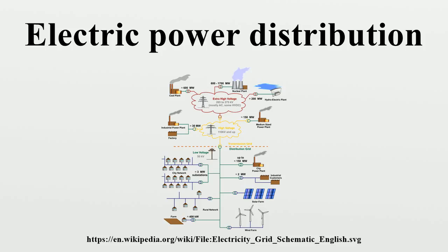Most utility customers are connected to a transformer, which reduces the distribution voltage to the relatively low voltage used by lighting and interior wiring systems. The transformer may be pole-mounted or set on the ground in a protective enclosure. In rural areas, a pole-mount transformer may serve only one customer, but in more built-up areas multiple customers may be connected. In very dense city areas, a secondary network may be formed with many transformers feeding into a common bus at the utilization voltage. Each customer has a service drop connection and a meter for billing.